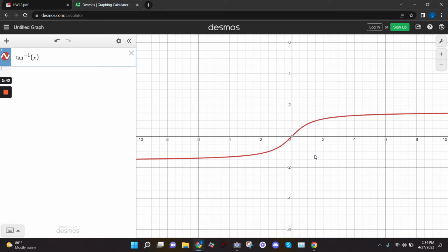But when you start adding these, like resistors and capacitors or inductors and capacitors, then you get phases between negative 90 and 90. Because now you have a piece from the capacitor causing some shift this way, and a piece from the inductor causing a shift this way, and you get some resulting phase shift. But a pure capacitor is always negative 90, pure inductor always positive 90, and resistor always 0.